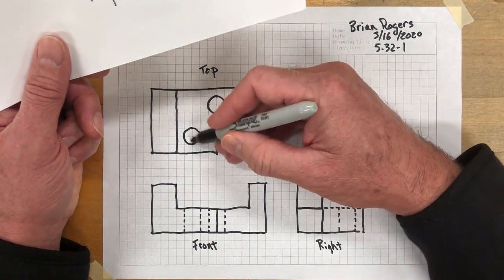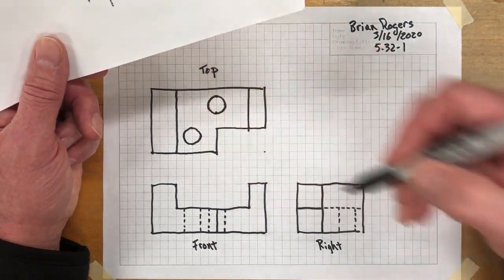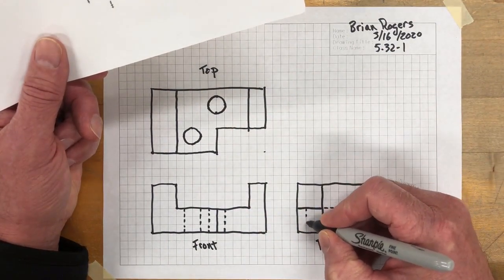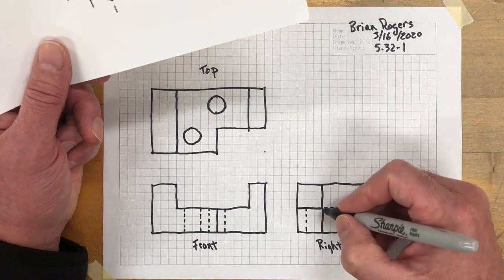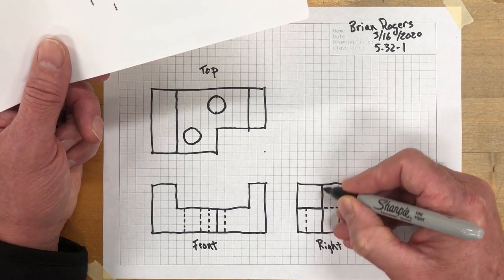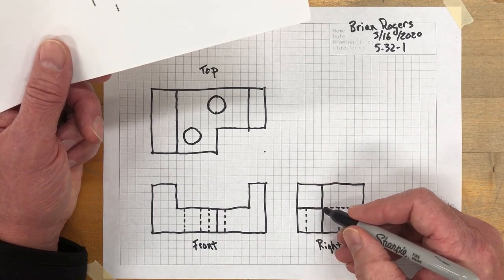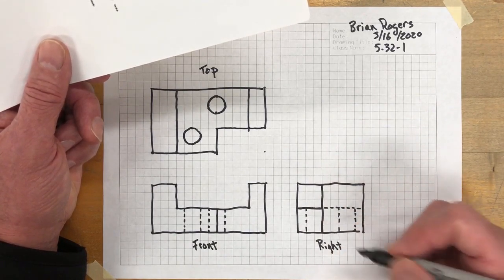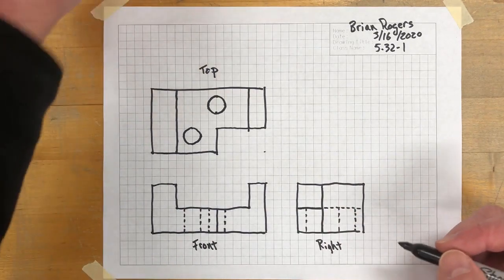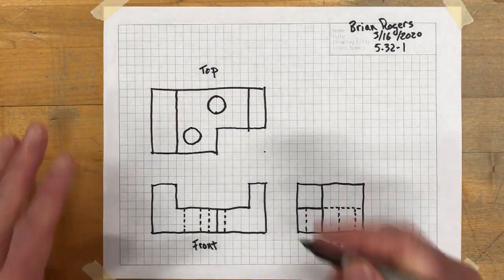And now I've got the frontmost hole. Same thing. It's 1/4 inch from the front edge back toward the back, hidden line there. Then I'd like to put a matching hidden line right here, but guess what? I've got an object line in front of it, a visible line, and placing a dashed line over that is not going to help. So at this point I've got all the details for this particular drawing.